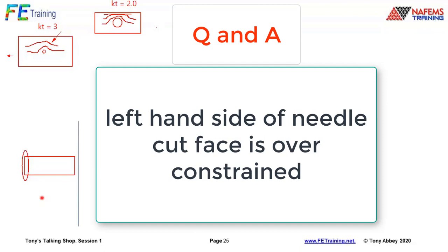Elephant's footing is a phrase we use because we lock that dimension in. This dimension wants to shrink naturally. So we get a section which looks something like this. It runs in and then expands out, like a sideways view of an elephant's foot. Yes, we inhibit the natural tendency for this end to want to shrink.